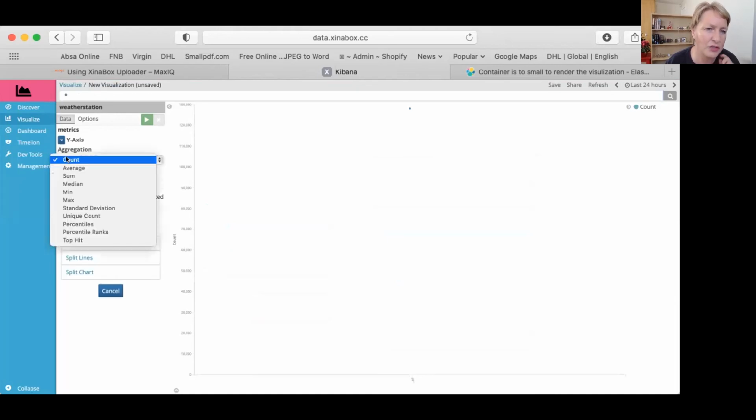The thing you need to do is always use average. The reason you want to use average is that your sensor is recording data every 10 milliseconds, but a data point can only refresh every 5 seconds.